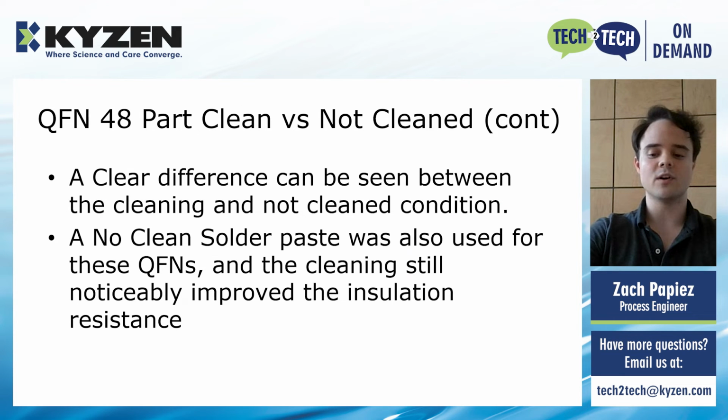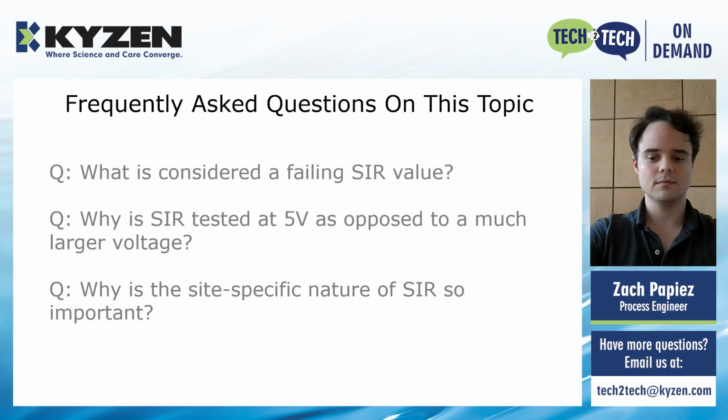The fact that a no-clean solder paste was used must also be duly noted. The residues left over from a no-clean process are usually much less active, but SIR was still able to detect a clear difference between the not cleaned and clean conditions. Even with a no-clean solder paste, a clean board is still better than not.